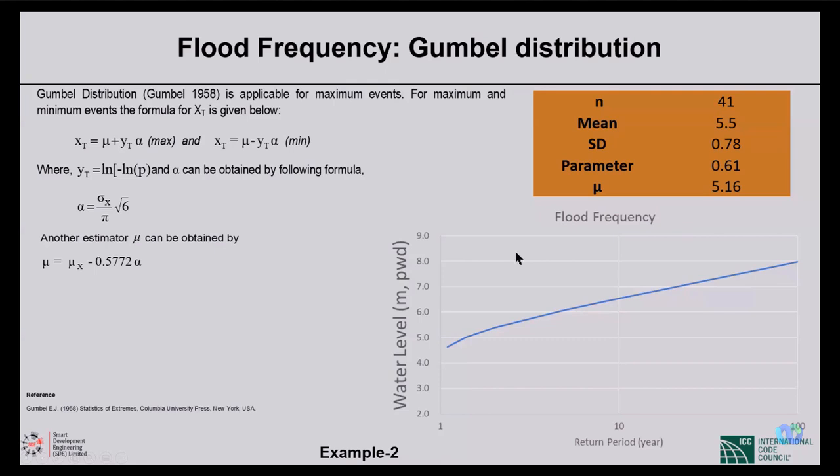So if you fix your 100 year return period for Dhaka city, in the southern portion you have to go for 8 meters. But it varies, right? For your land area, you have to do the leveling between the gauge station's zero value and the land area where you built. Then you put in a pillar with the top level mentioning your benchmark. So with the benchmark, if it is 1 in 100 year, that is the level. This level will change